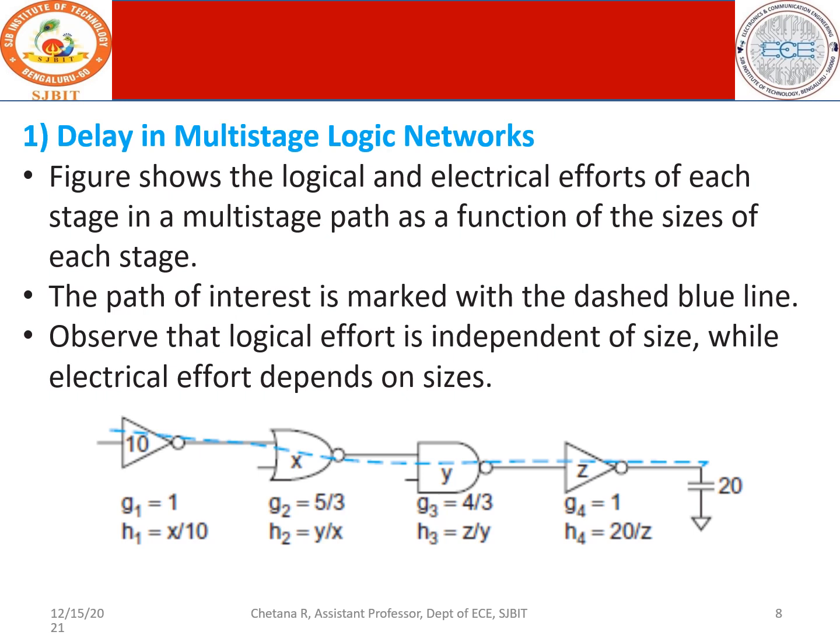We have the first device, which is the gate. The gate input is 1, and the propagation delay value is given here as 10. G is 1, based on the size of this inverter, 3 by 3.